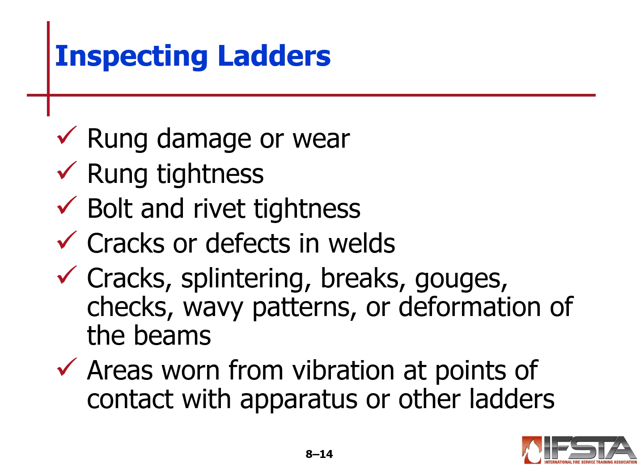This is a key area where we can get some wear, depending on what type of mount system you use. Traditionally, the ones that hang off the side, where the ladders hang from the rack and are locked in, are the ones where you get the vibration wear. If they're bedded flat in the back of the truck, they usually don't get a lot of vibration wear.